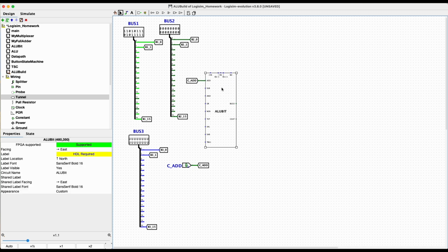It's always a good idea to just drag something a little bit, make sure the wire follows it, because sometimes you think you got it connected, especially when you zoomed out. It's close, but not quite connected. And if you drag it, you can see, oh yeah, I didn't quite connect that. So that's one nice little debug thing you can do to make sure you really get your wires connected.